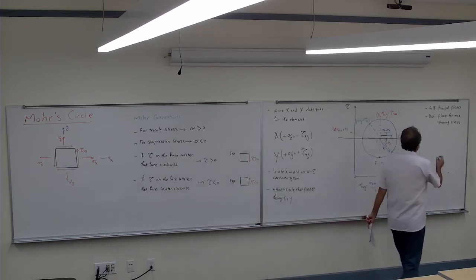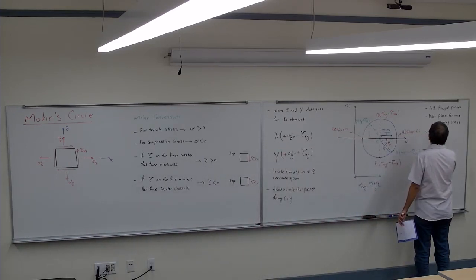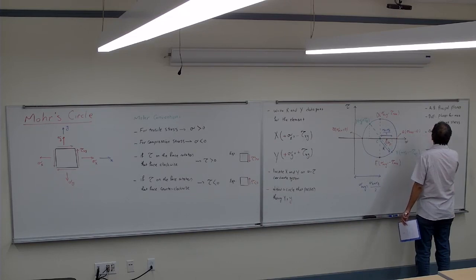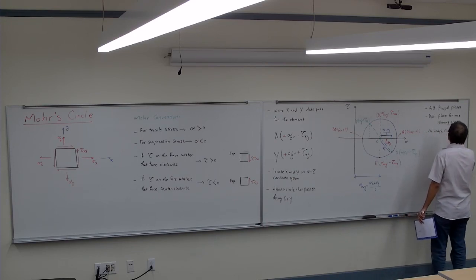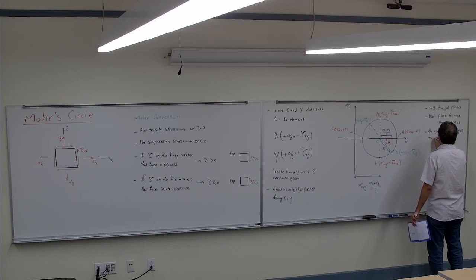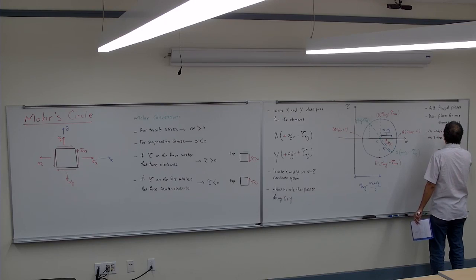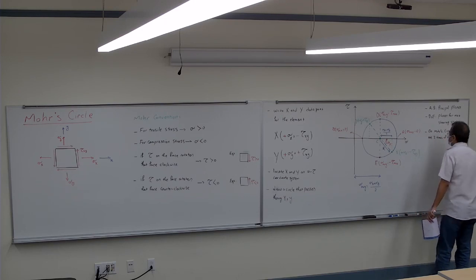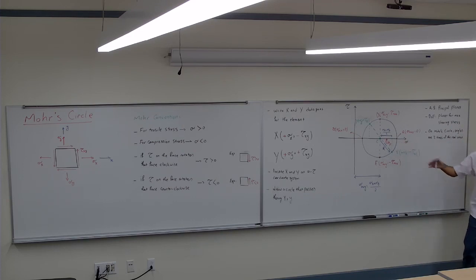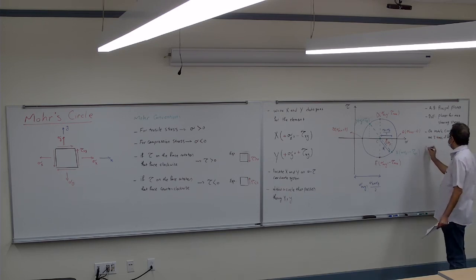The next is on the Mohr diagram circle. Angles are 2 times the real. So if the angle on the Mohr diagram is 60 degrees, it means that it is 30. If the angle on the Mohr diagram is 180, it means that in reality it is 90. So the real one is half of that.